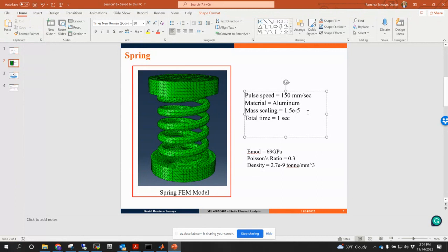Right. But however, if you have something really light and you add a pulse, what's most likely gonna happen? Finding the equilibrium in something light is really difficult. So what do you usually do? You do mass scaling, right? So you increase the mass of the system, so whatever pulls you up to the system, then the system's like, I didn't feel anything. This is how I'm gonna behave if you give me this pulse, right? So it's a good modeling technique if you want to get a sense of how things behave, but it is not really accurate, right? So today we're gonna use it.